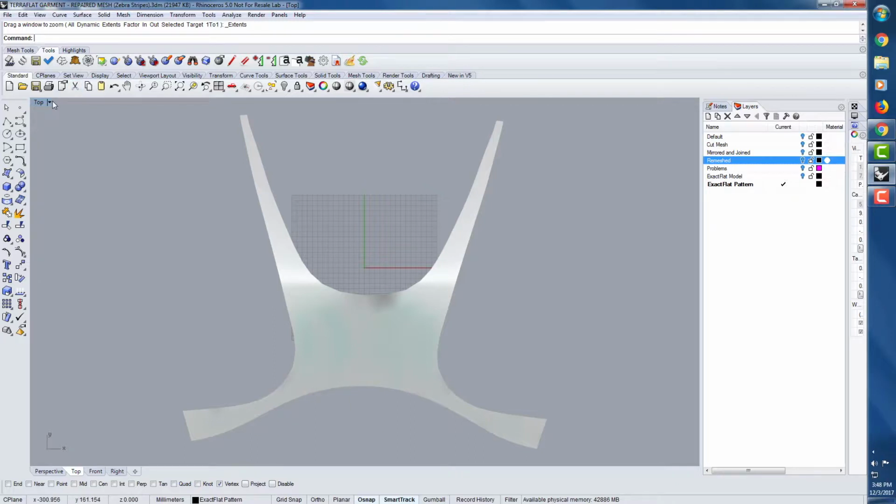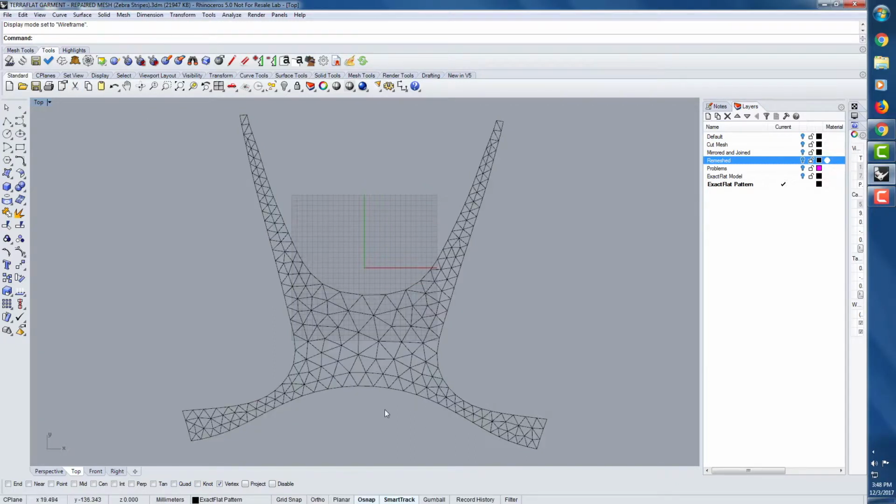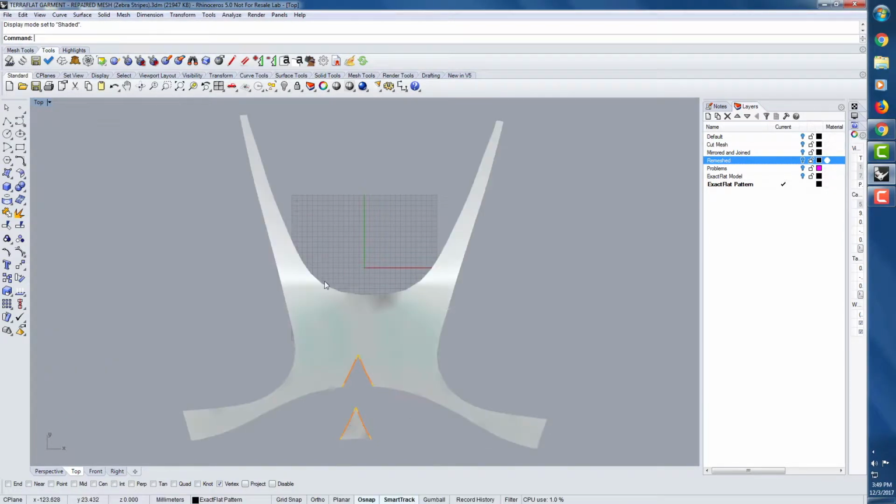and I'm going to go into my wireframe, and I'm going to cut out a segment here to emulate a dart. Now, the best tool for this is, well, I can use a couple. We have just a manual cutting tool, so I can start here, go here, and then go back down and cut that out. So if I move this, you can see, I'll turn on my strain or my shaded view. You can see I've removed the dart there.